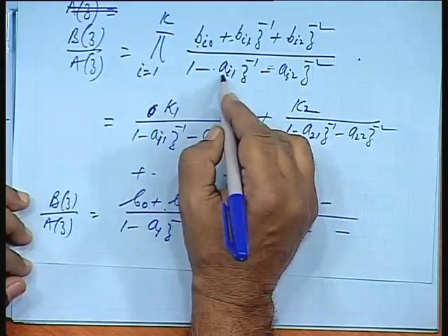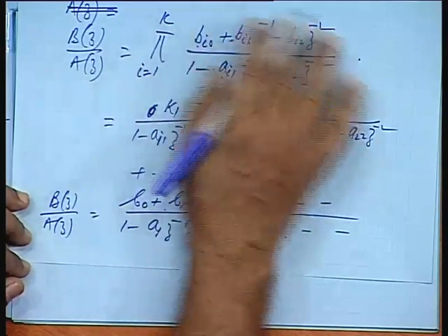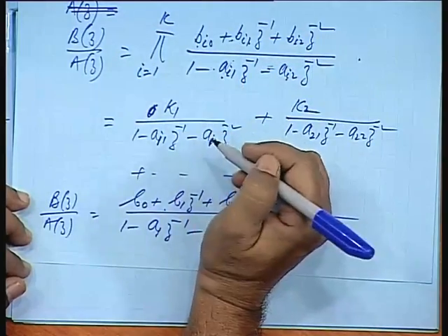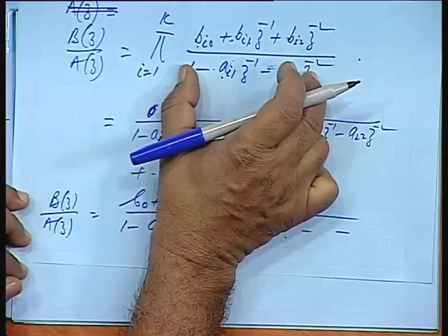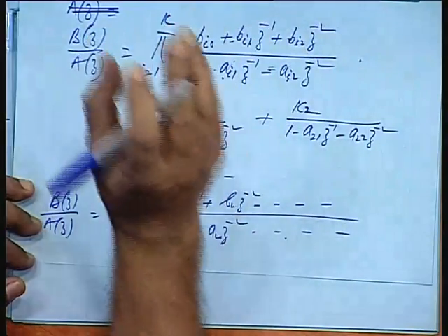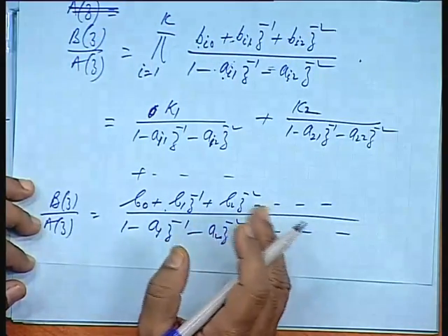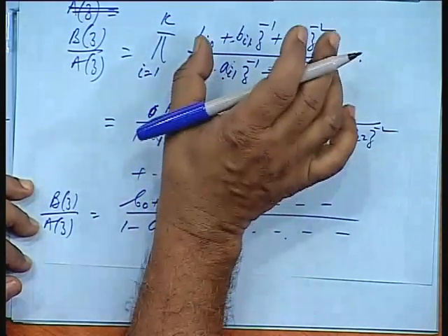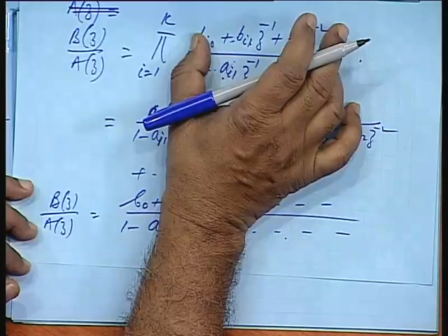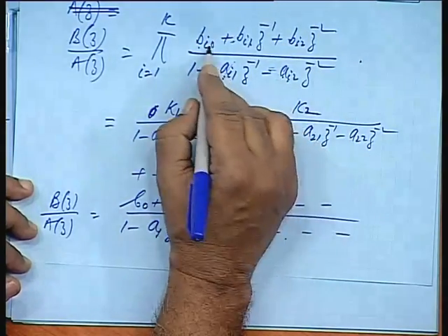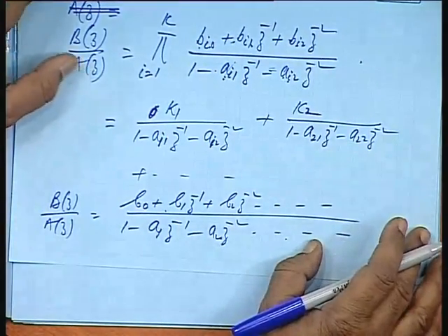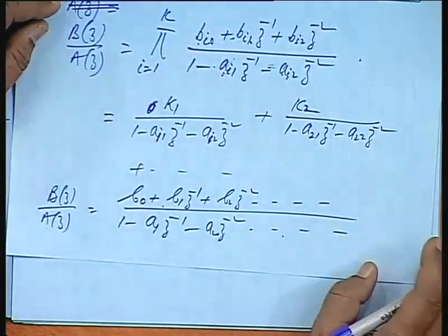Here quantization of a coefficient, suppose forget about others, just one coefficient is changed, only this pole pair will be affected, others will not be affected. So, here we are restricting it within a certain group, restricting the sensitivity of a particular group of poles and zeros with the variation of these coefficients. So, this is much more robust.